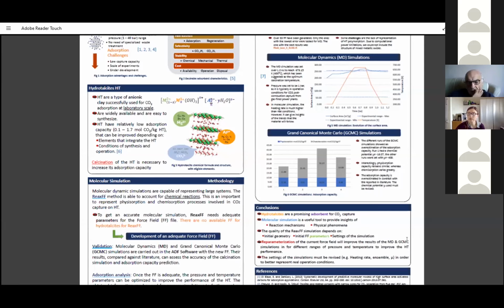Around 300 to 350 would be the best, because if you get to 400 again, which is when you calcine the material, and go further, then instead of this porous structure you get a spinel, which is a crystal salt. That doesn't have the characteristics we need. So as long as you do the desorption between 300 and 400, you're on a safe range.